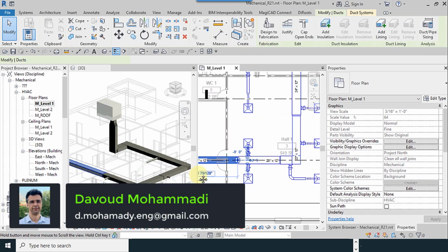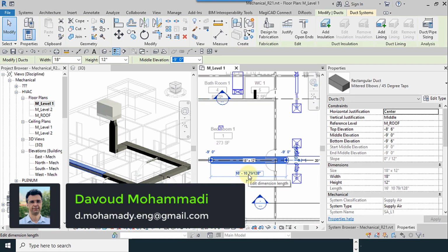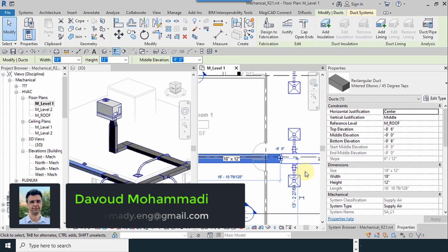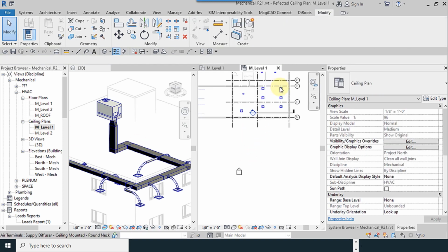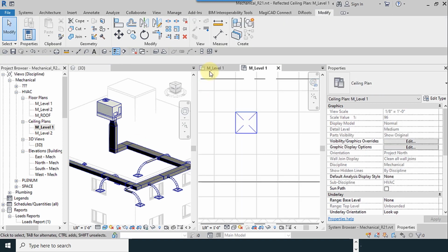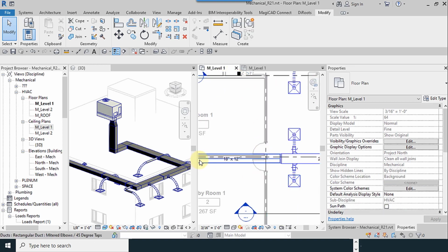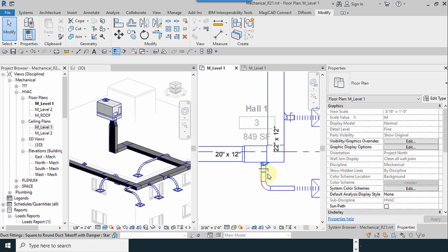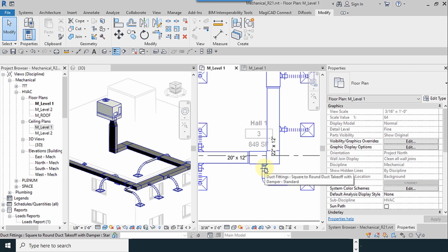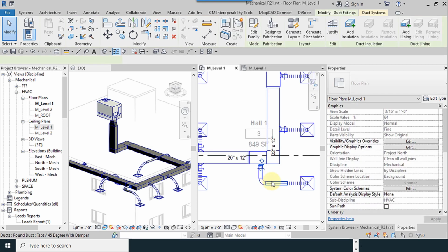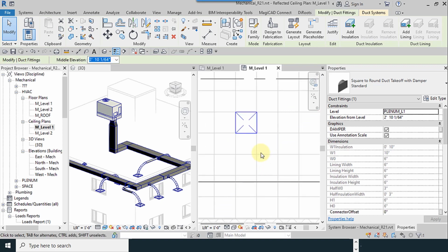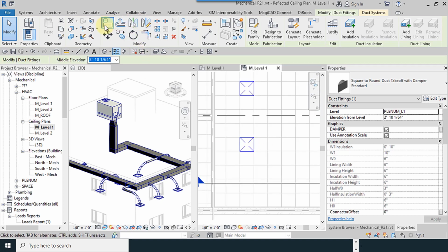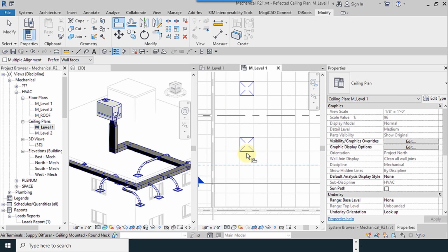Okay, I have to move this duct downward a little. If we have the space problem, we have to go to the ceiling level and move the diffusers a little to the bottom. I have to do this, and so I have to rectify this one, and I move it to the left. Approximately, I move it as the size of one cell.